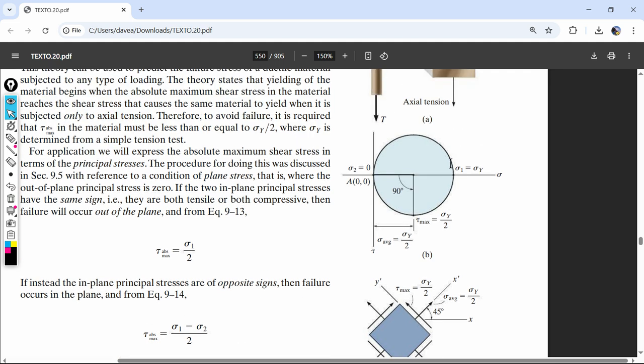The Mohr circle goes this way as the positive direction. This is your positive shear stress. We have to draw a Mohr circle to relate to reality, and we do so by saying that this is your tension and compression, these are your normal stresses, and this is your shear stresses. And this is the positive direction. You would just call this the positive y direction, just downward. That's positive.